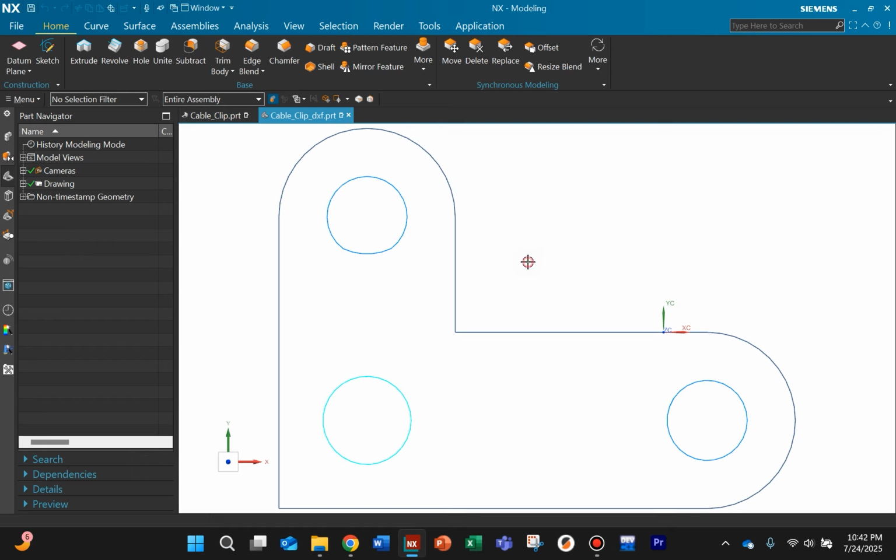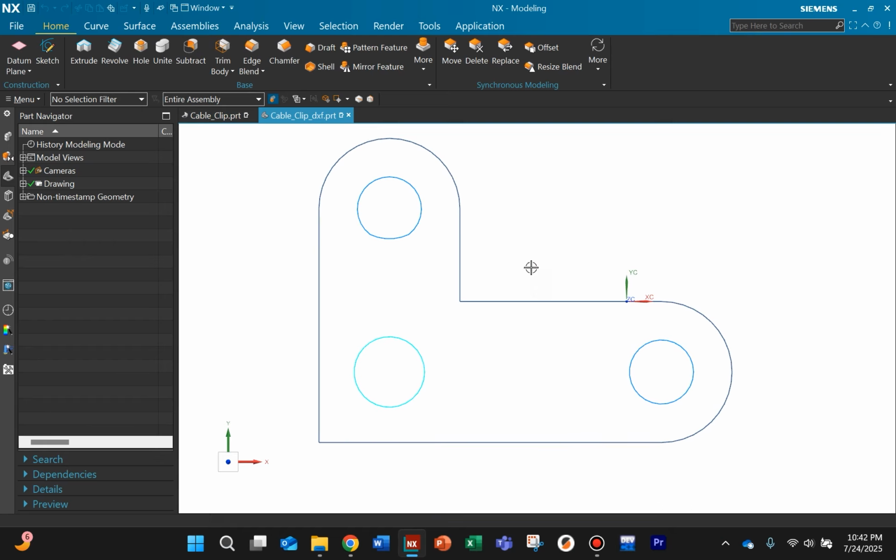And I'm going to open that up. All right, here's that DXF file that we just exported. Notice that the bend lines are not there. We just have our holes and the lines for the perimeter. So something like this it would be good to send to get plasma cut or laser cut, just the lines that we want to actually cut.